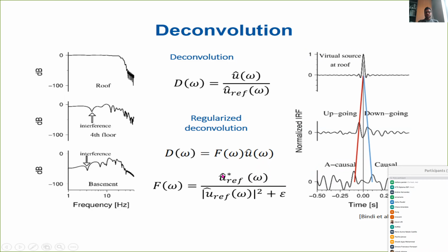If you then look at the denominator, which would become the spectrum of this multiplied by the complex conjugate of the other spectrum, you immediately recognize a term which is equal to the cross correlation of the two signals. What is different is that you have a sort of normalization for each frequency that depends on the power spectrum of each frequency at the reference station.